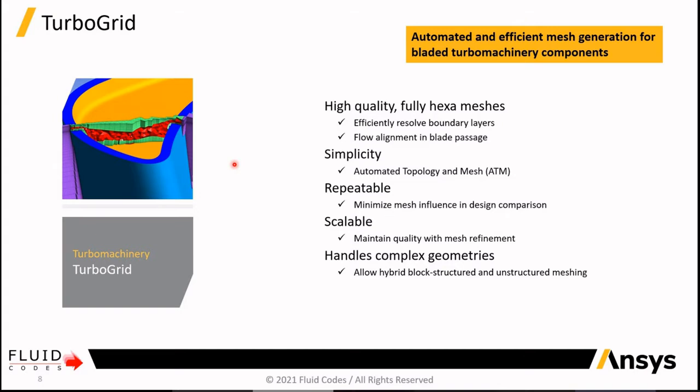So in case you're dealing with turbo machinery, pumps, turbines, compressors, stuff like that, you might already know that the mesh is very important, even more important than usual, I would say. It's always important, yes, but for turbo machinery applications, we might need to have some regular pattern. And this regular pattern of the mesh is given by structured hexa elements, a structured grid with hexa elements.